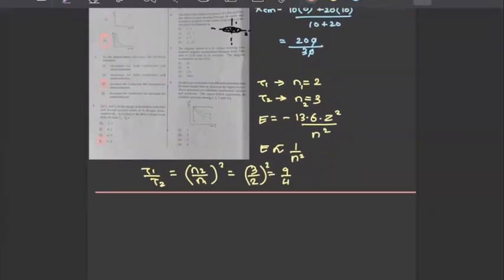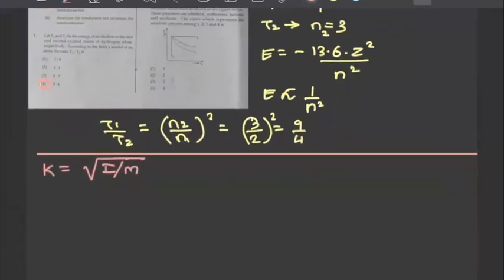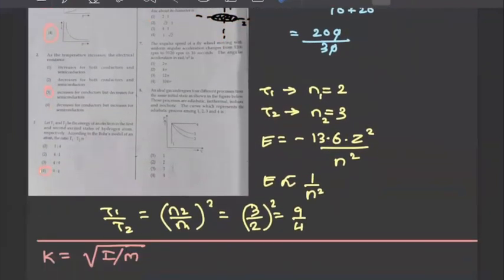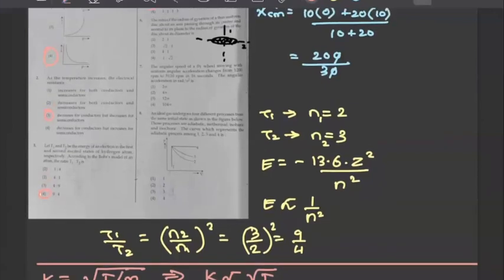Right, so the radius of gyration formula, I is mk square, or k is basically square root of I by m. So mass is anyways a constant for both of them. So what I need to do is get a ratio of the moment of inertia about first the main axis of the disk and second the diameter. Okay, so I can now say k is going to be proportional to root of I. So k1 by k2, if I want, it's root of I1 by I2. So what I really need to do is get I2.